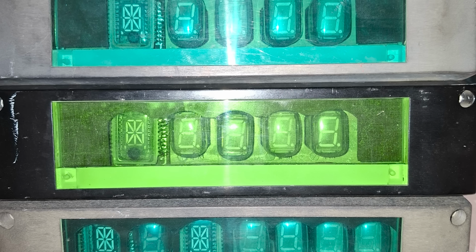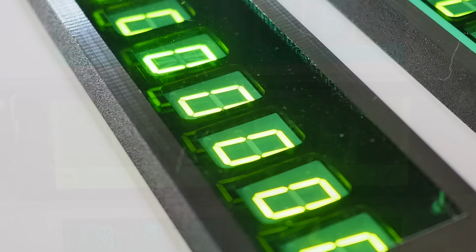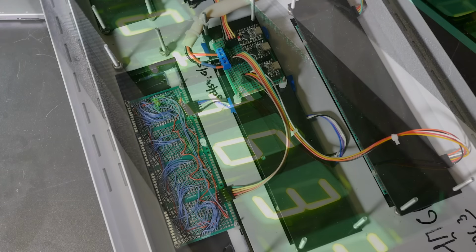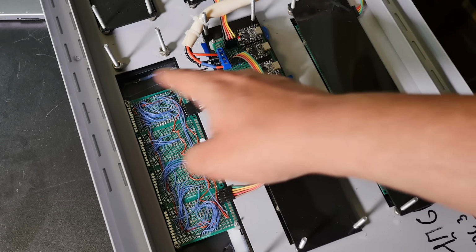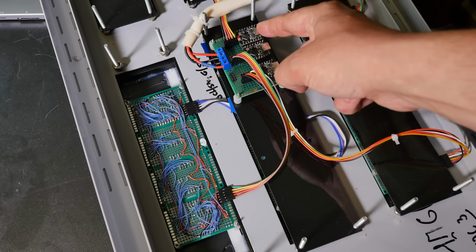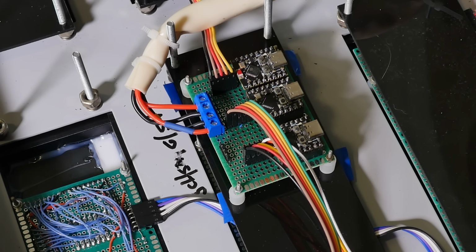How did the nuclear power plant used to deal with repairs and replacements? Well, I have absolutely no idea. And that's why we instead used green LED matrices. They are controlled by chains of shift registers, which are connected to a few ESP Mini. Each acts as a character generator for 2 complete displays, and all that sits on one shared I2C bus. So the entire assembly needs just 2 data lines in addition to power.